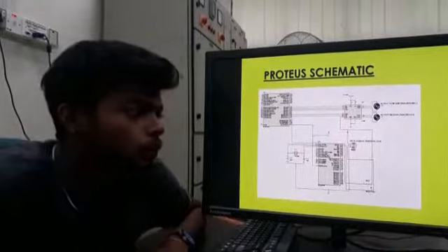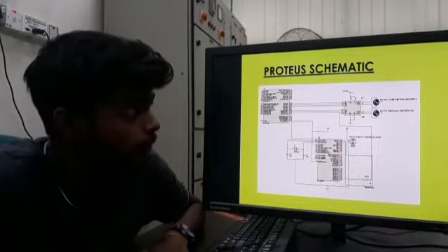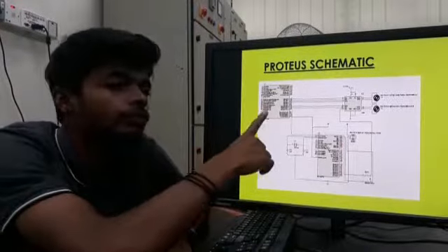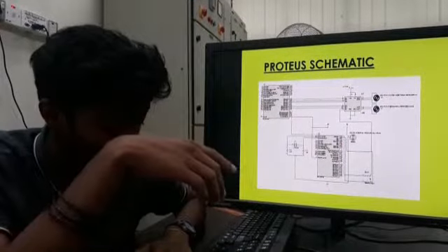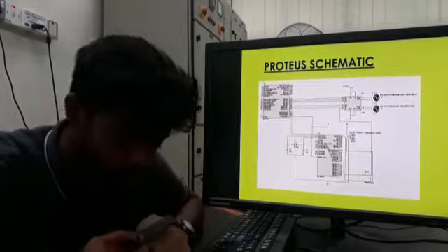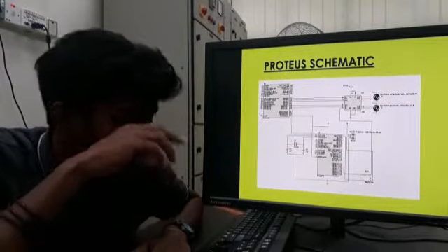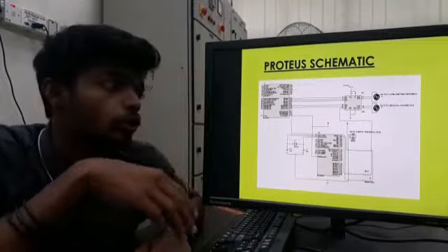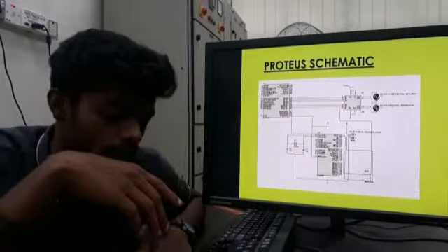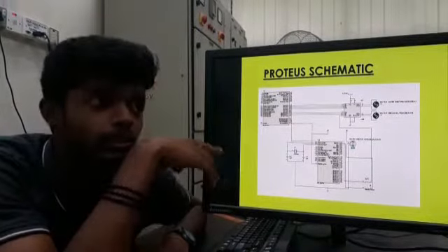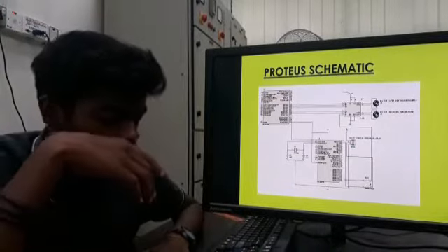Proto schematic of our boat. This schematic has two PICs. One is the 18F4550 and the other is the 18F877A. The 4550 controls two motors, which are being controlled by the motor driver, the L293D, and the PIC 16F877A controls the servo motor.